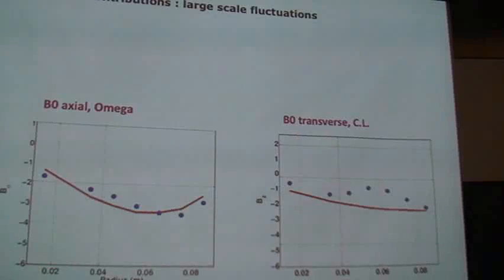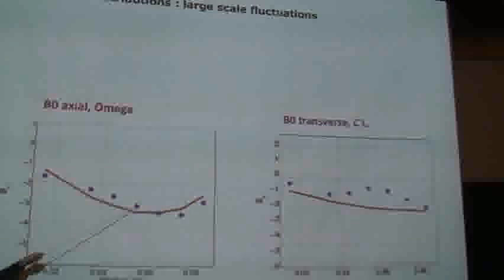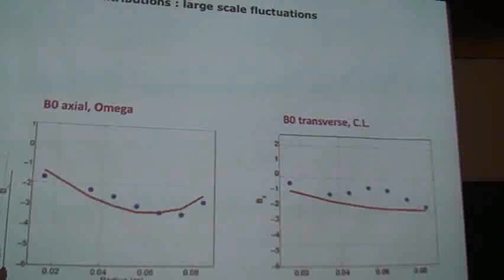here. What I've done is insert into the flow a probe that has a number of sensors in order to record a profile. And then I'm plotting that profile as a function of time. Each of these blue points is the mean value which I was showing on the previous picture. But if I take a low-pass filter, those mean values will evolve slowly, on the order of the frequency of rotation. It gives you an idea of the stability of those induction effects that you have, and that's what it looks like.